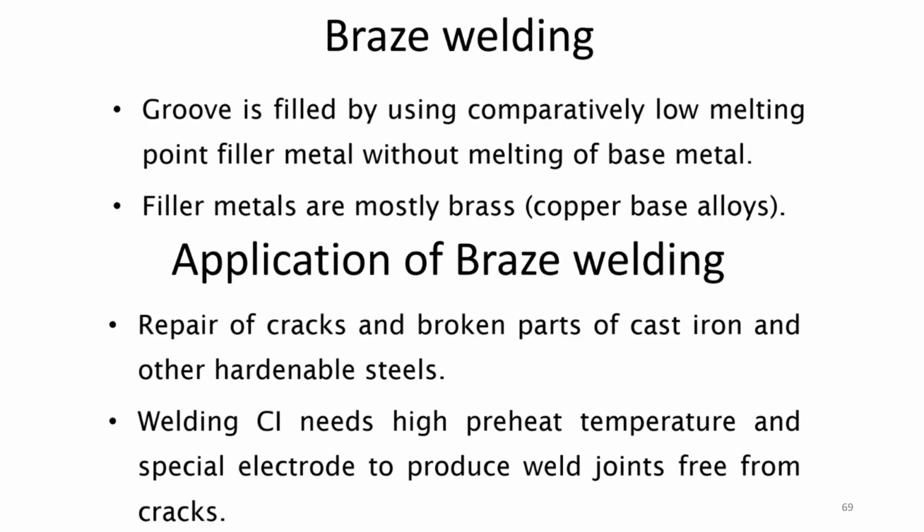Application of braze welding is for repair of cracks and broken parts of cast iron and other hardenable steels. In the case of welding of cast iron, it needs high preheat temperature and a special electrode to produce weld joints free from cracks.